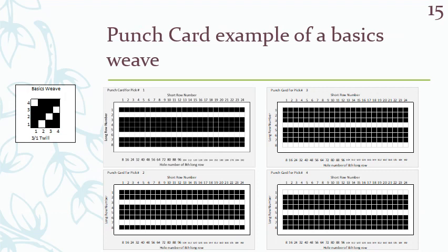For example, let's suppose we have this 3 by 1 twill weave. This 3 by 1 twill weave we need to produce with the Jacquard weaving machine. For the Jacquard weaving machine, we punch the cards. So for the first weft, our design reads one up, one down, two up. We need to fill this in the whole card.